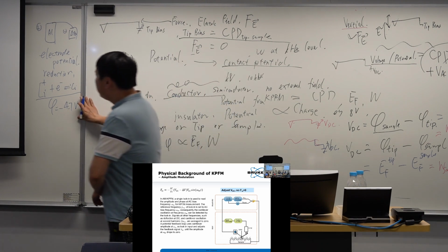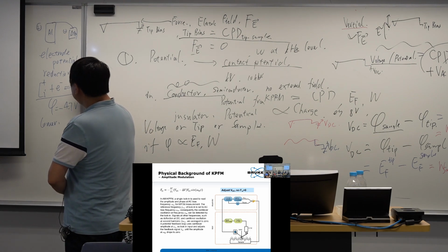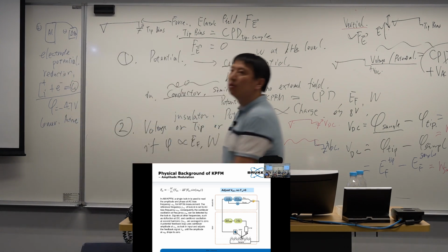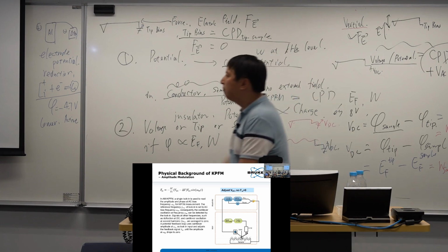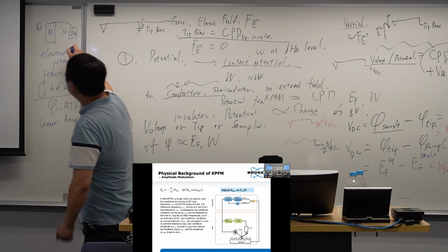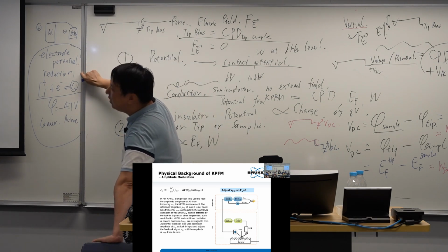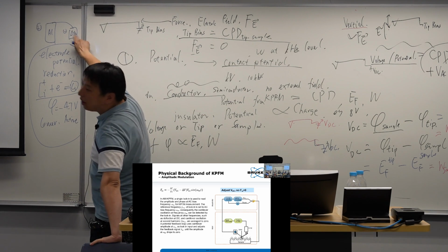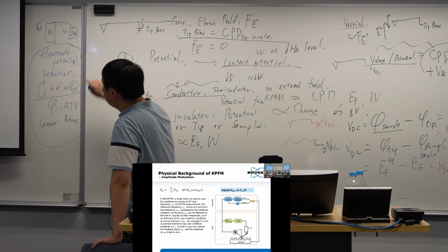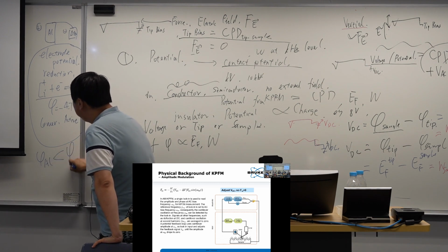And when this value is lower, it means this metal is more active. There are some researchers from batteries or corrosion who all know this kind of electrode potential. But the electrode potential is not the same as our contact potential here. So from the electrode potential, we will definitely know phi aluminum is smaller than phi gold.